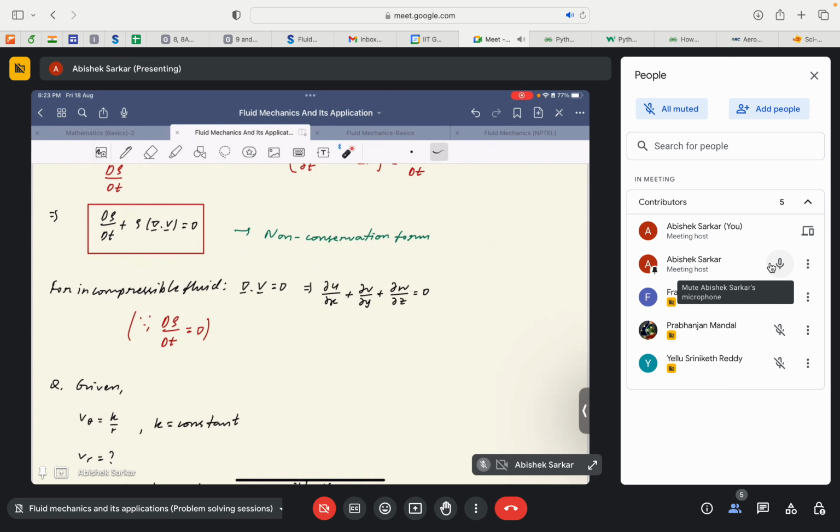It's very important. Here you may feel that we are discussing the steady case only, but no. For steady as well as unsteady cases, if the flow is incompressible, this is the mass conservation equation. In Cartesian coordinate system, it gives us dou u by dou x plus dou v by dou y plus dou w by dou z is equal to 0. Cylindrical and spherical coordinate systems will each have their own respective form. I have not written them, but for the Cartesian coordinate system, this is the form of mass conservation for an incompressible fluid.